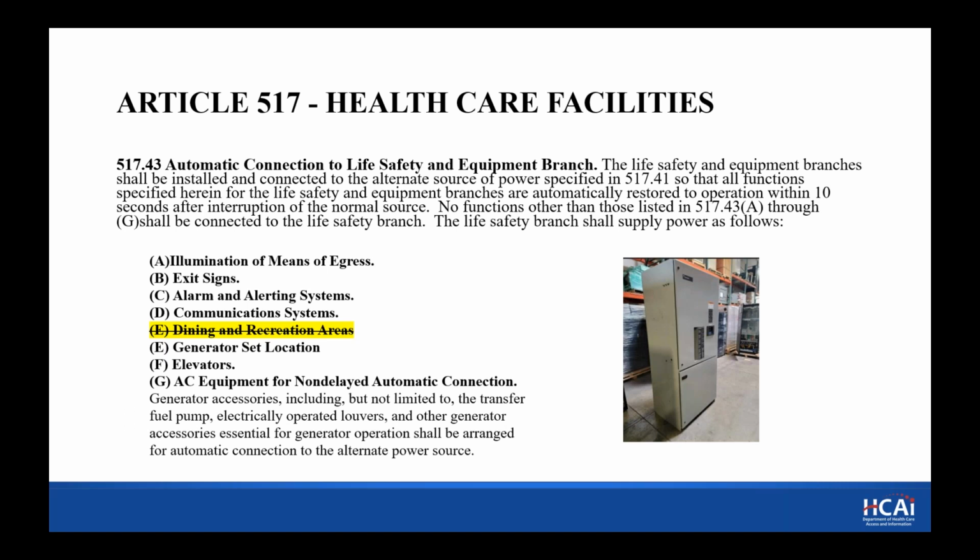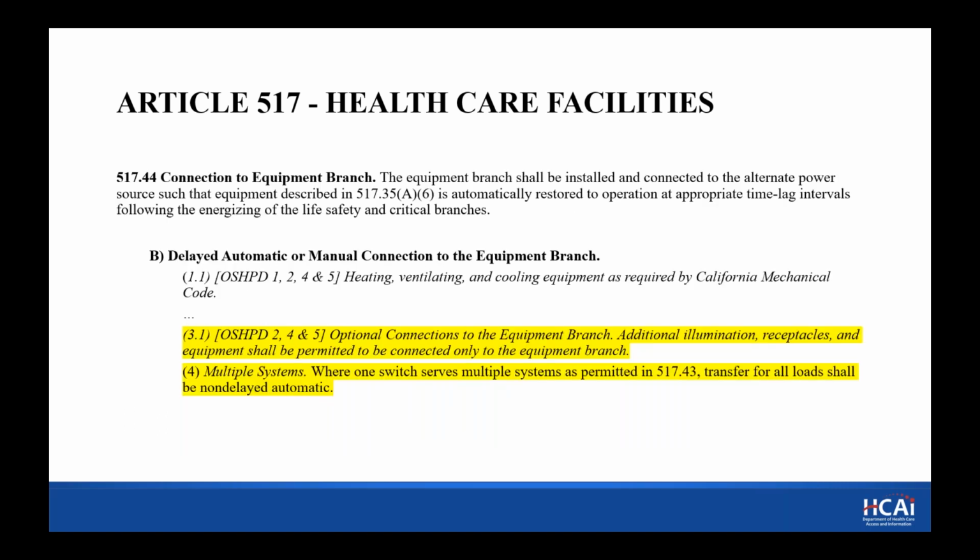517.43, now we're talking about SNFs, and we see that the requirement for automatic connection to life safety and equipment branch, essentially they're removing the requirement for dining and recreation areas to have life safety lights. 517.44, essentially here they're talking about connection to the equipment branch in our SNFs.